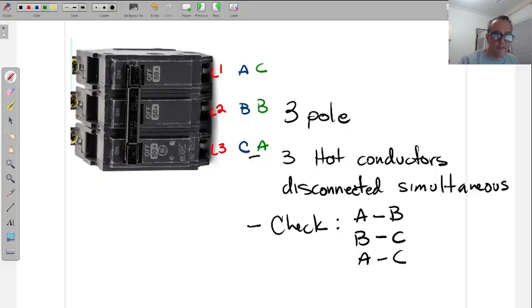It doesn't really have to go in that order, and sometimes for motors, if you did the motors classes, you'll have done motor reversing, and when you do motor reversing, you switch up some phases. Reversing the phases will change the direction of the motor. Usually what we do is you only change two of them. So you would just change the order, like it would be B, A, C. You just flip these two.